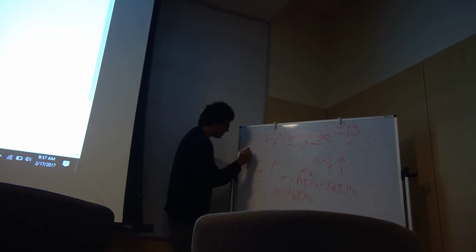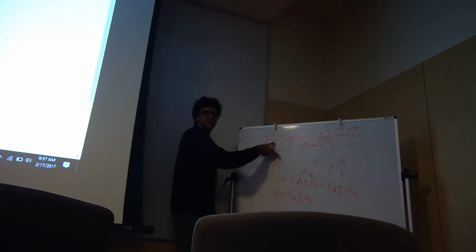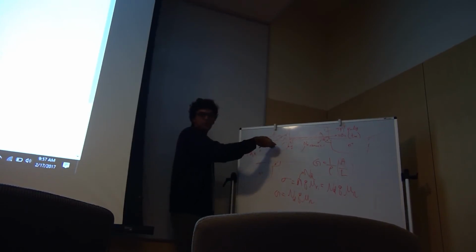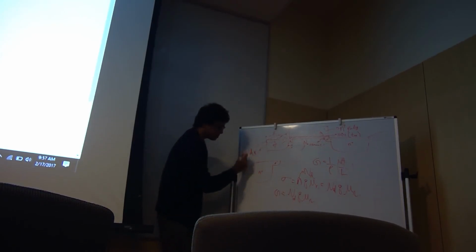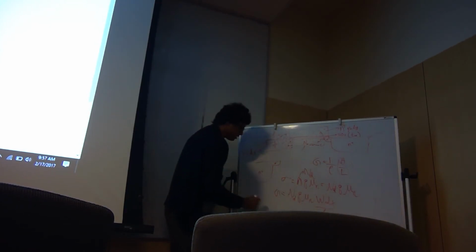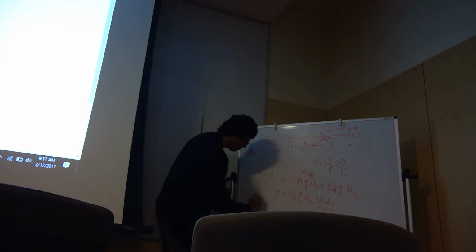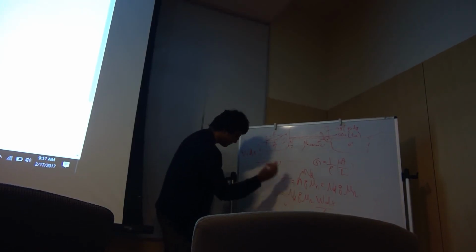You need to actually end up integrating this over this distance, integrating over the profile of your doping, because this is where you dope your material along the x direction. So this is just W dx over length. So your resistance is going to be 1 over this. You have to integrate this.